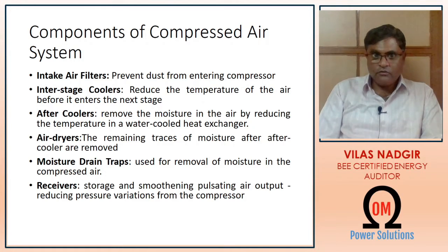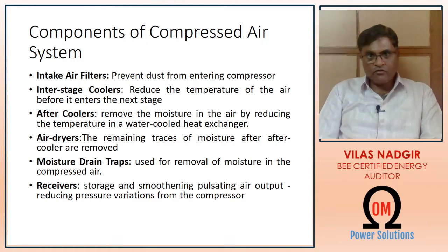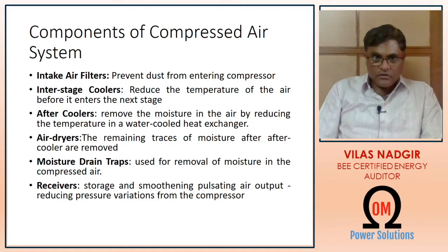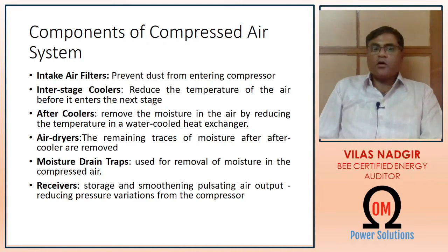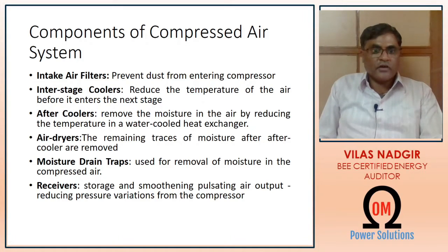People usually confuse between interstage coolers and after coolers. Although both interstage coolers and after coolers reduce temperature, the ultimate goal of these components is different because interstage coolers are used to cool the temperature, whereas after coolers are used to remove the moisture from the compressed air by cooling the compressed air. This is very important to understand.